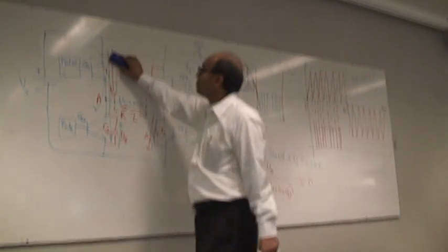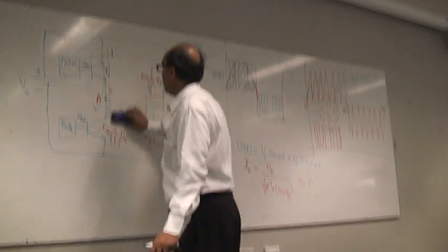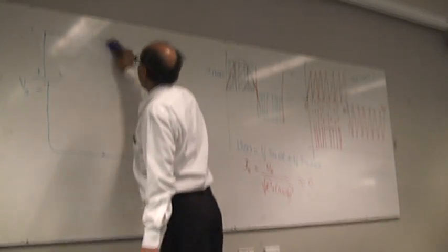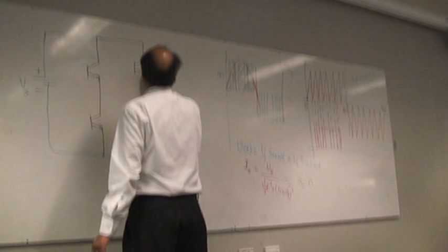So this is one of the most important requirements for the control circuit. Who will design that? The control designer, whoever it is, needs to design that. I need to draw again. So that part is the most important part, that your circuit should not energize two transistors in the same leg at the same time. That is valid for the 3-phase too. So for 3-phase, we have 3 sets of legs.